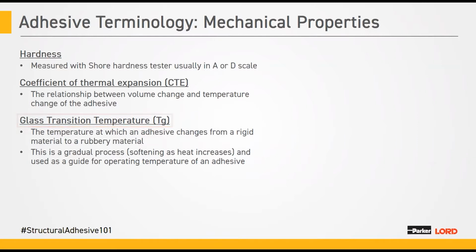Think of this more as softening on thermoplastics. So it's a range of temperatures, not just an absolute. It's often expressed as a single temperature value, but know that the softening occurs over a range as a gradual process. The best example to think about is if you're thermoforming plastic parts, knowing that the material will begin to sag or begin to reach that rubbery state at one temperature, and when it's finally used, it may have to reach a second temperature where it's more elastomeric, more stretchy, to do the vacuum forming.